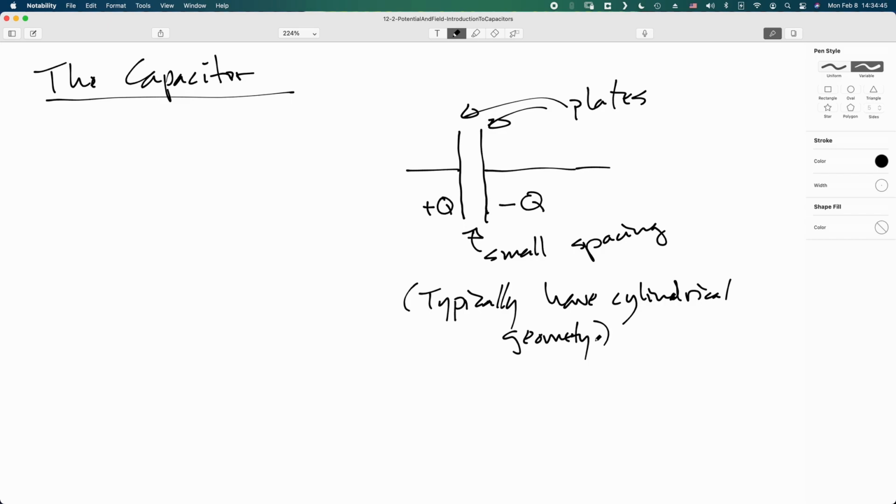The way this actually gets done is you take two thin strips of aluminized mylar and intersperse insulating material between the strips and on top of the other strip. And then you roll the whole thing up like a jelly roll. That basically creates, more or less, a parallel plate capacitor, but it's been rolled into a cylindrical shape. And it's more correct to model it as a cylinder.